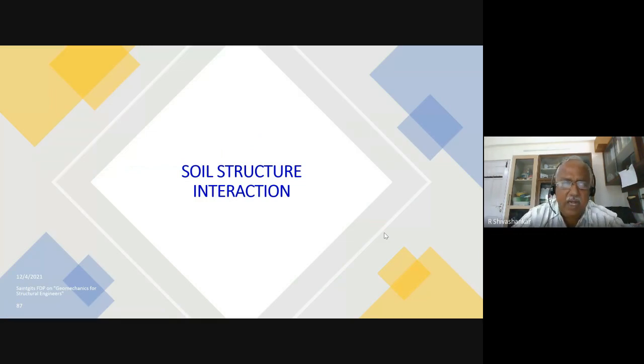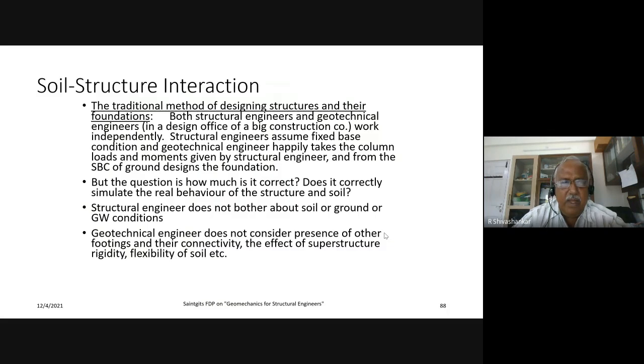So I would like to briefly touch upon some of my experiences with soil structure interaction. I owe it to all my PhD students because I learned a lot from them. And as I said, the traditional method is that the structural and geotechnical engineers work independently. The structural engineer assumes a fixed base.